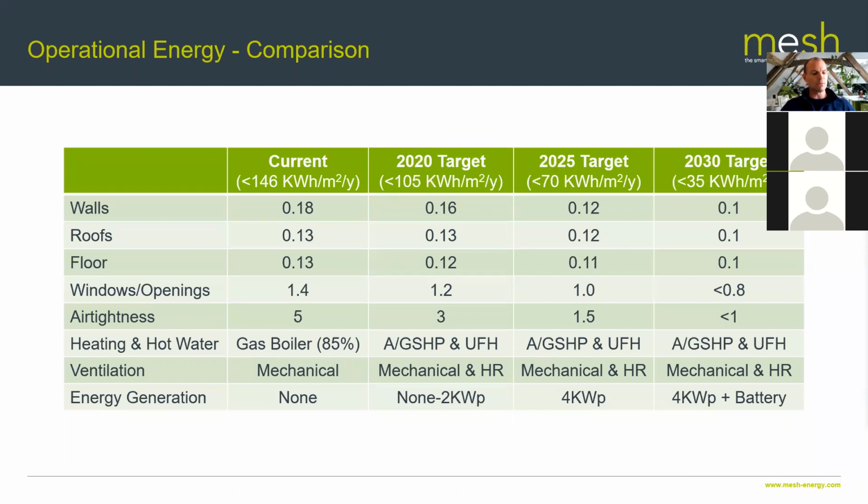We've shown this slide before, and it's a reliable guideline on what has to happen with U values and various technologies as you go through the RIBA targets. The first 5 lines cover U values for key external elements in a building, and then we've got air tightness mentioned as well. As you go through the columns, you can see that the U values are getting lower and lower.